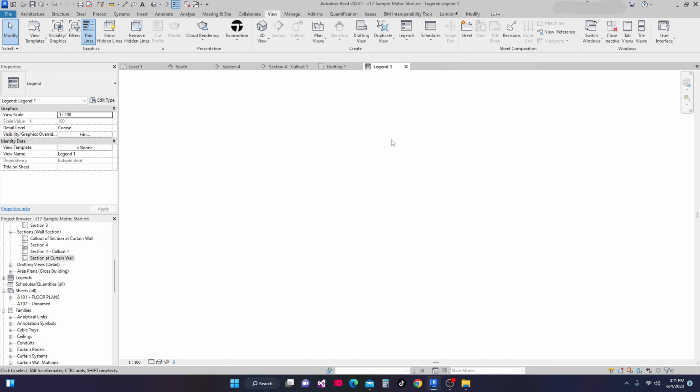So what is detailed line? Let's talk about detailed line. In detailing, there are a variety of tools or parametric tools you can use. You can use this tool to create strictly 2D geometry or to augment details you are trying to create from 3D plans, sections, or call outs.